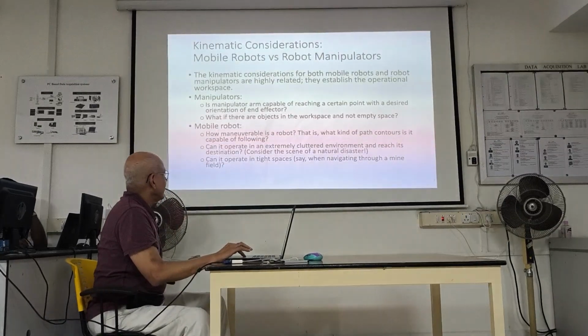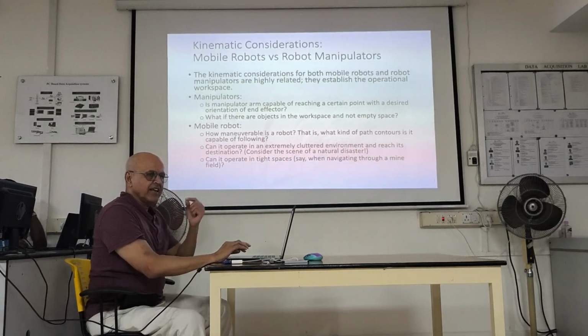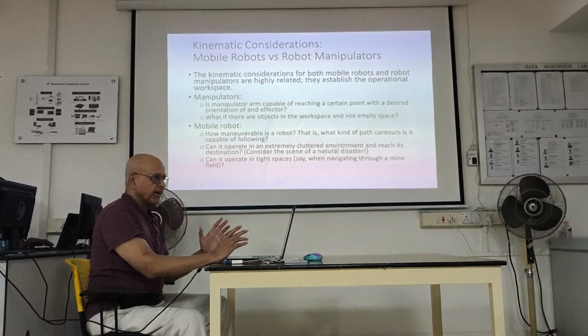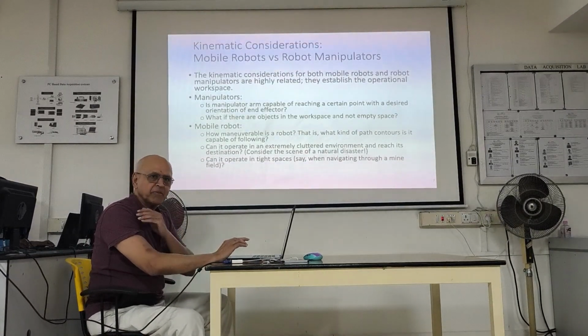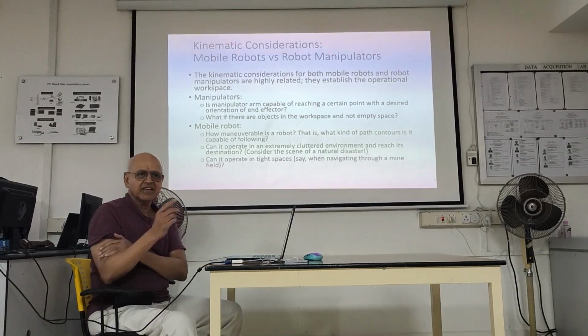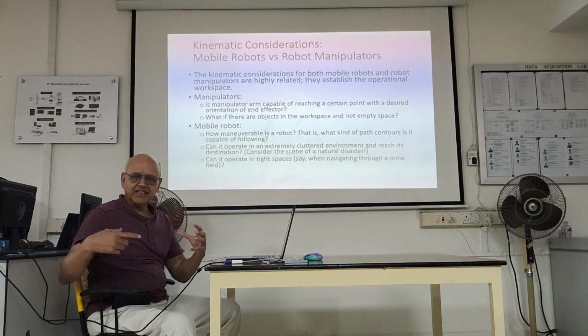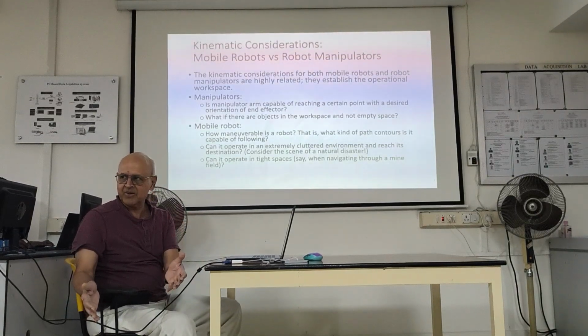Mobile robots, on the other hand, have to deal with the real world. People walking across, right? And suddenly you encounter a bad road, then you still have to be able to drive on it. Odometry is horrible on bad roads. You know why? Because if you have potholes, then the wheel rotations don't mean the same thing as on level ground.